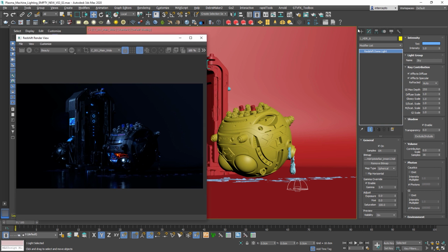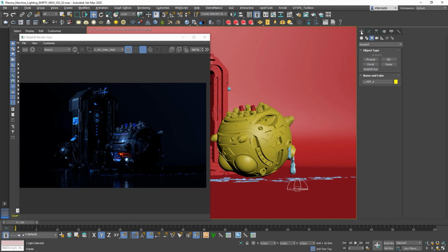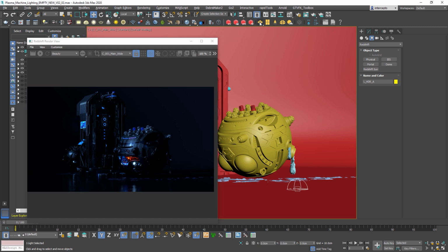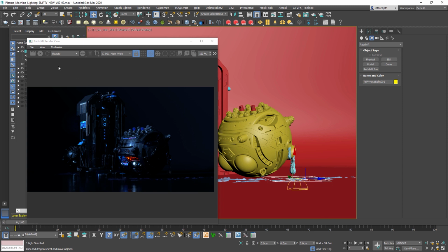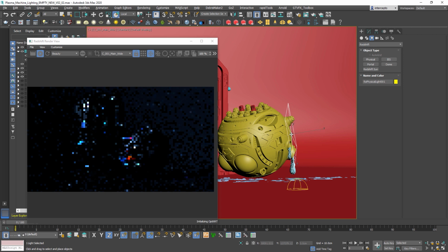Let's continue adding other lights. So back to the create menu, or because I have a toolbar over here, I can just directly access some of the lights. So this icon is to create an area light, and we'll just click on that area light, and then we'll place it in the scene. Let's run IPR again. Okay. For this light I'll place Y, and then as I click on that light and start to move it around, I can position it and rotate it based on the normal of the object. So we'll put it over here for now and push it back.